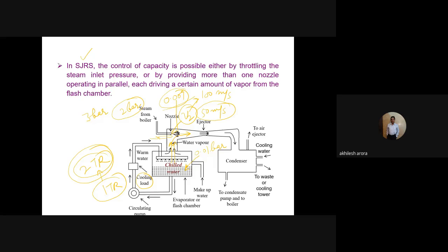You can always reduce the pressure. Suppose air is passed with a very high velocity over some pan which is containing moisture, so what will happen? The moisture will also be entrained along with the air, and this is because the air has the momentum. It will create a sort of suction effect, and that suction effect will reduce the pressure over the surface of the water, and the water will be evaporated. Okay.